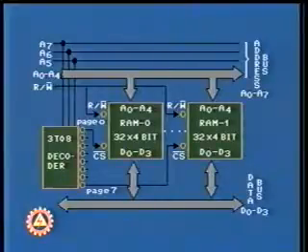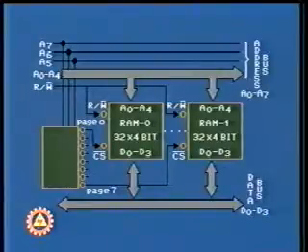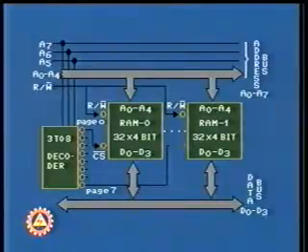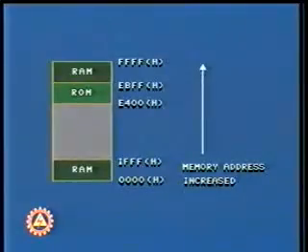The page address decoding is done with a 3 to 8 decoder and the output of the decoder is connected to the CS bar input of the memory block. The blocks of memory locations allocated to ROM and RAM are usually shown pictorially in a diagram known as a memory map.